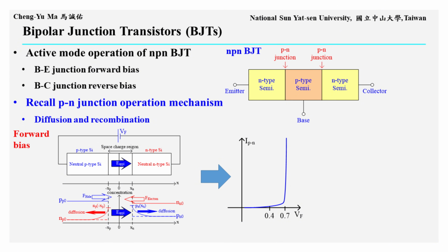In general, current begins to appear when the forward bias is greater than about 0.4 volts, as shown in the IV characteristic curve. When the conduction current becomes large, the forward bias is usually around 0.7 volts. Therefore, for DC circuit analysis of a forward-biased diode, we can use the 0.7 volt constant voltage drop model for quick estimation.